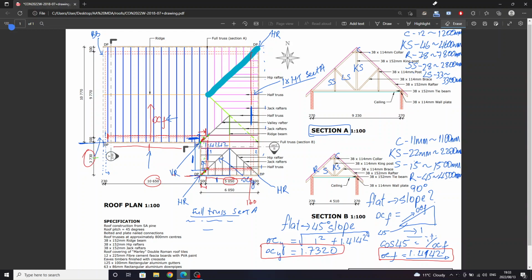So what you might do is you go timber less than 2.4 meters. You do your standard description for the timber, whatever component you're describing. It's less than 2.4 meters, and then you're going to collect all the pieces that are less than 2.4 meters.